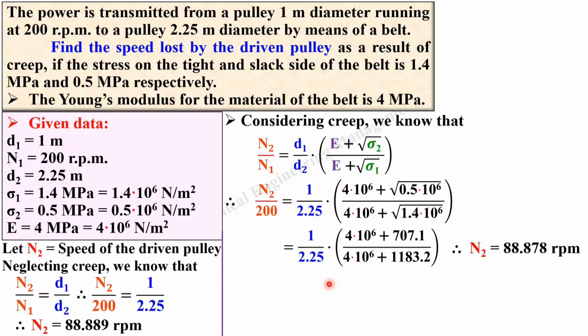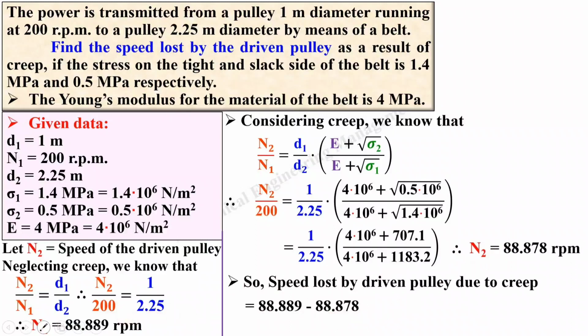Now you can understand what the value of the speed lost should be. Can you give me the answer, my dear friend? How can you find the speed lost? Yes, it is very simple. The speed lost by the driven pulley due to the creep will be the difference of these two values: 88.889 minus 88.878. This is the speed lost due to the creep. So that is your answer.